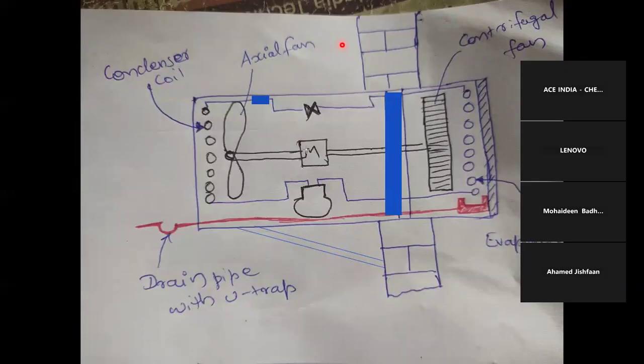So as per the natural law, a normal conduction or convection will take place. That means a heat exchange will be triggered right in between them, isn't it? So if that heat exchange triggers, what will happen? You will not be getting a proper refrigeration effect, isn't it? So that's why we are implementing this kind of thermal partition in between them.